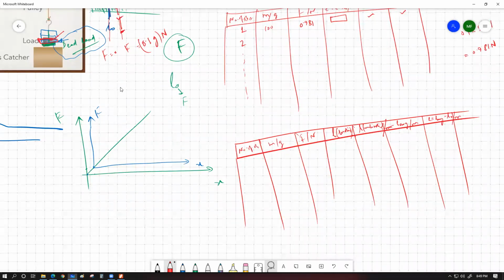So let's say we're going to apply 100, 200, 300, 400, 500, 600, 700. Okay, maybe we're going to do up to 800. Let's not go too much. So let's say we're going to do up to 800 grams. The recommended method over here is that once we do up to 800 grams, we're going to have only one reading because this is our last reading. We're not going to have any unloading level.